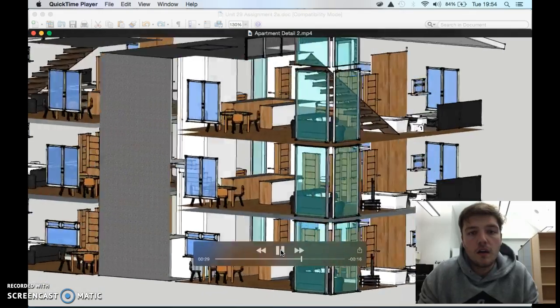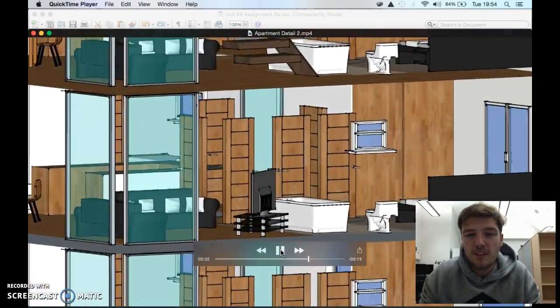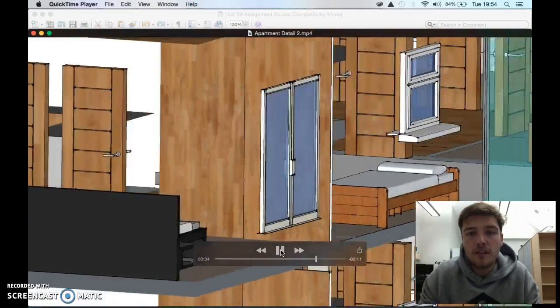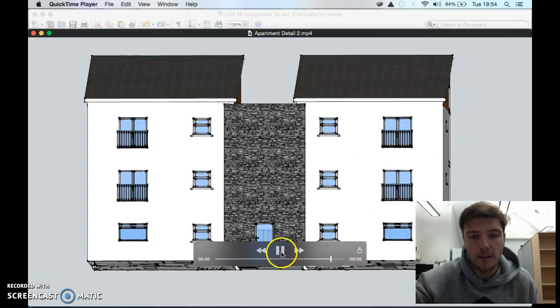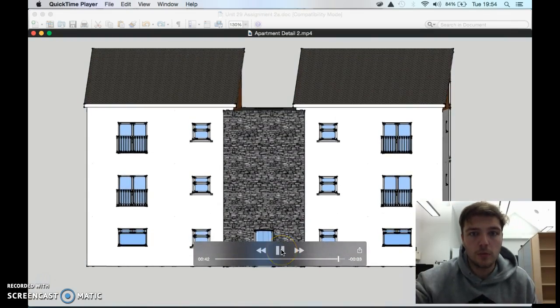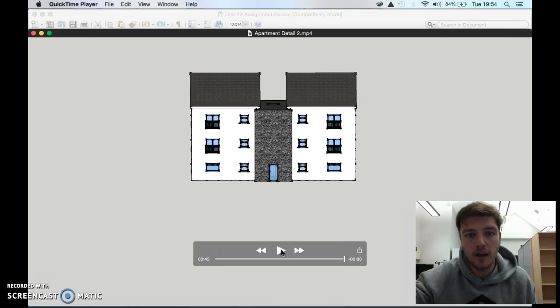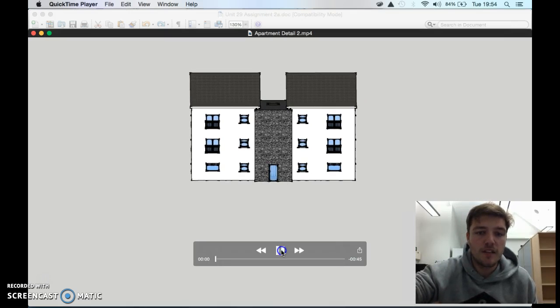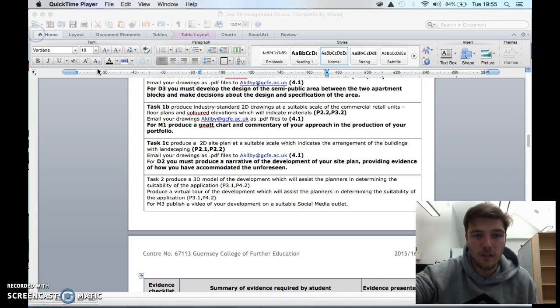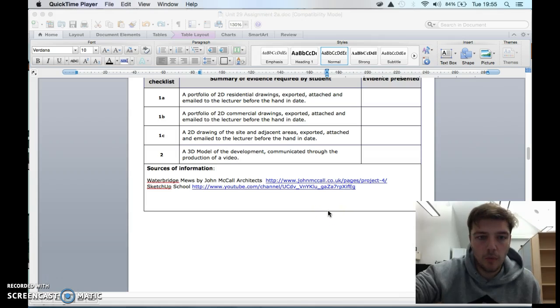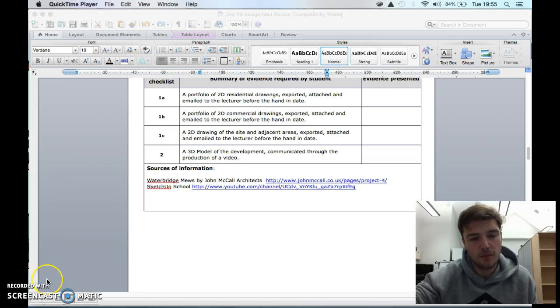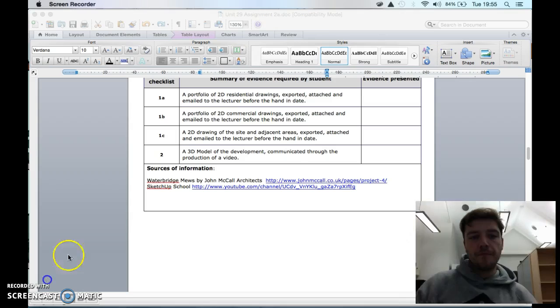For me, this does give you quite a lot of detail. If I could go back and start the project again and actually know the program a lot better than I do, I would have put external walls and internal walls, rather than just doing a wall layer. It would have been very difficult to go back and do it retrospectively, as it's not as easy as CAD, because you've got to pick up the wall element and all the lines for the walls, and you may miss some, or they might end up on the wrong layers. It's something I'm going to have to be very aware of in future.